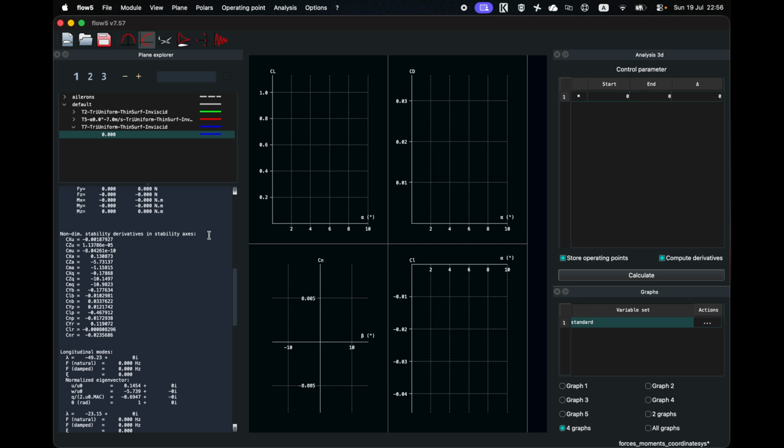An increase in side slip, that is the nose of the aircraft pointing left, leads to a restoring moment, trying to yaw the aircraft to the right. Since the z-axis points downwards in the stability coordinate system, this is as expected.